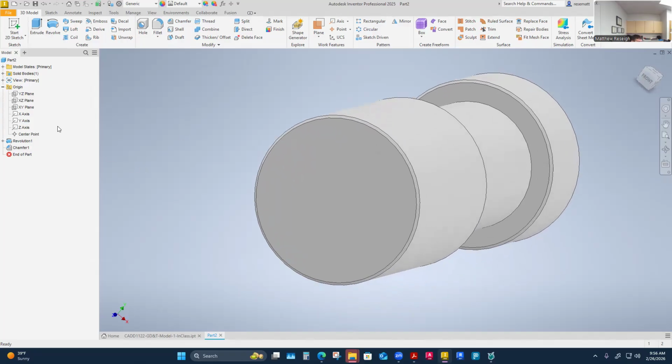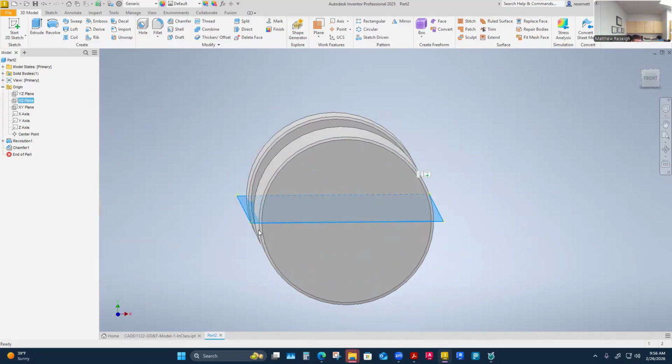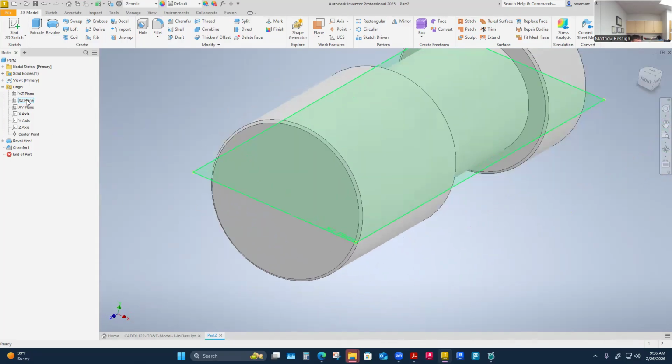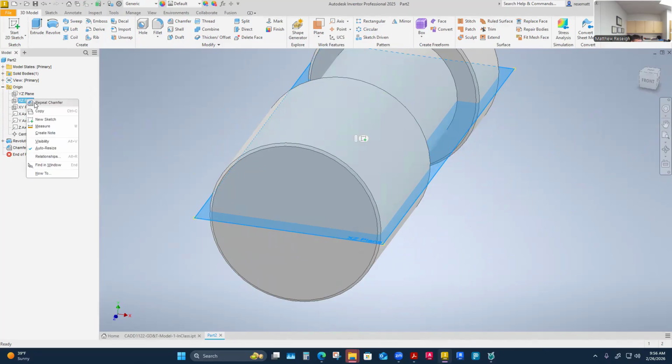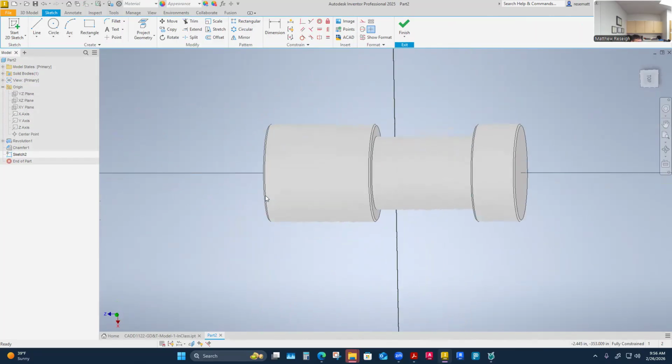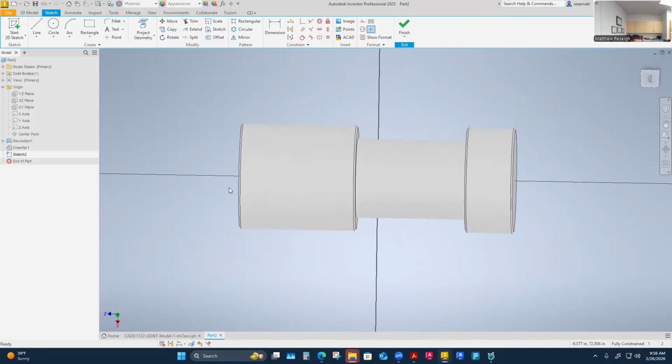And when I do that kind of stuff, I might establish center planes on parts still, rather than have a surface plane. But because this is the one I want to use to do this sketch right there, it's my XZ plane. I'm going to say do a new sketch here. So it orients it this way, but I can flip this around. I'm just going to do a sketch here. It shows that I'm on my top, which is good.